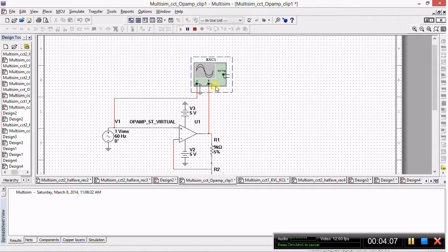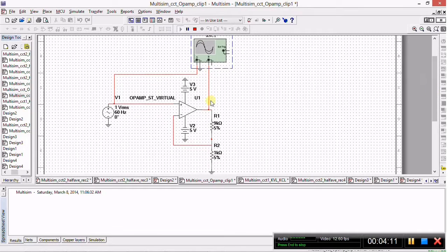This is why we have terminal B connected across the resistance R1, and A connected at the input. Only one of the terminals is grounded, which is A. You could have grounded B instead, because for an oscilloscope, the negative terminals are internally connected, so grounding one means you grounded the other.